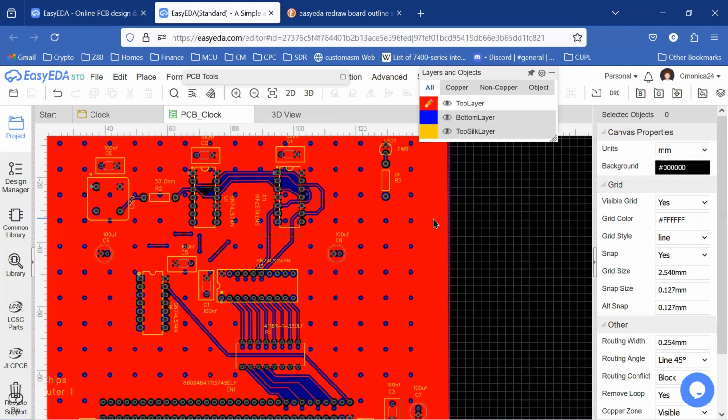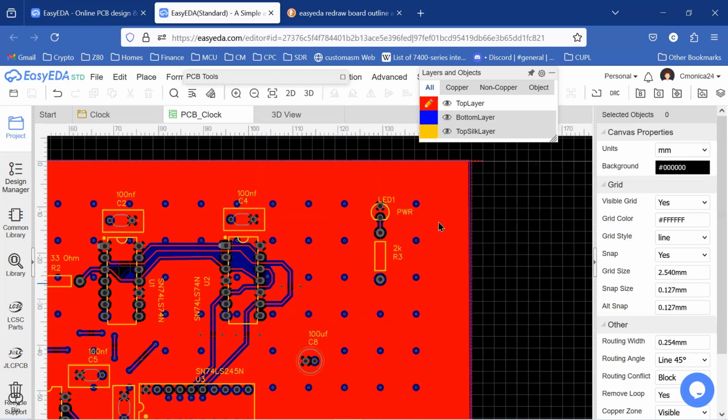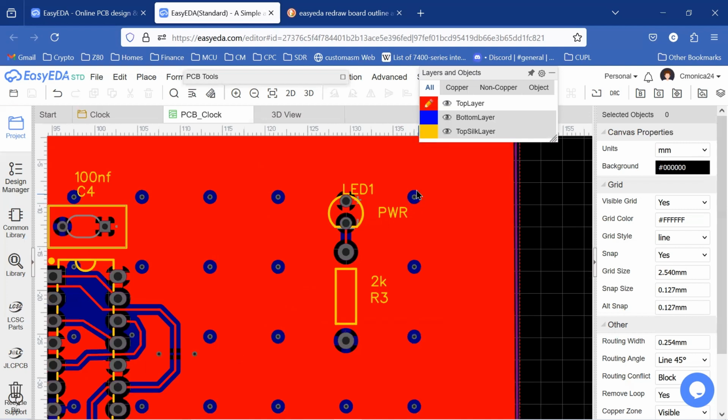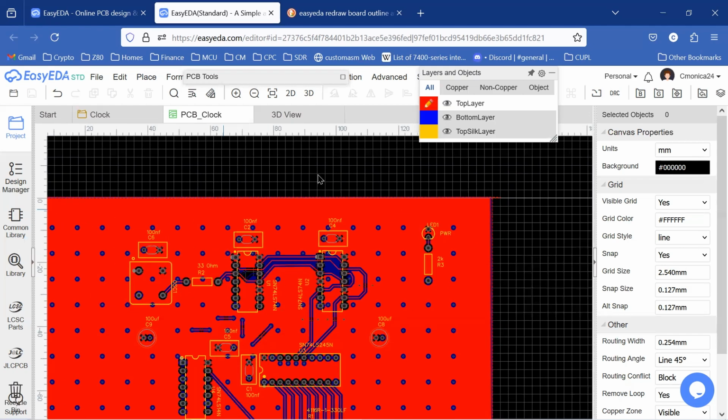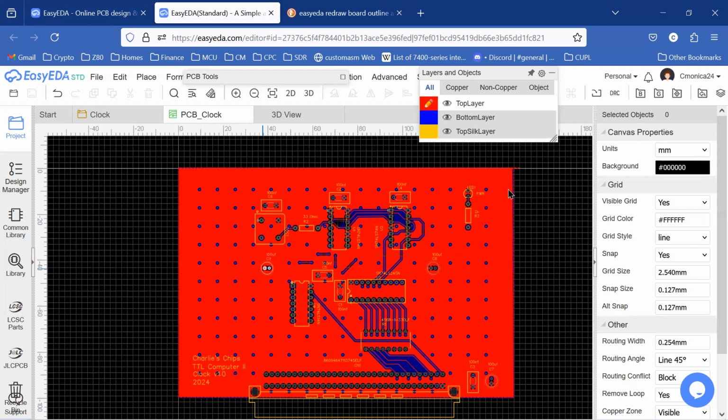vias. And what those vias are is really like a little copper tube that goes from the bottom, from the ground plane, up to the top layer of the board. It's not connected to the power plane. We see that there's a void there, but that is like a tube that goes right down to the ground plane. And what those function as is kind of like little antennas.